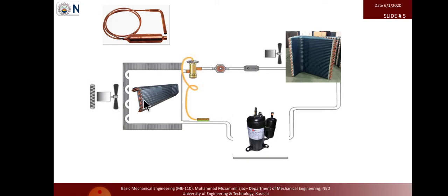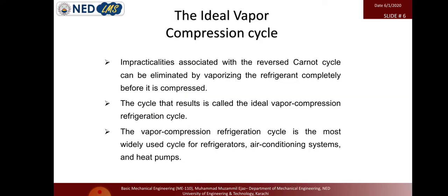It evaporates at 12 or 13 degrees. When the room temperature air passes over here, it contacts the refrigerant with room temperature like 25, 26, 27. So the liquid refrigerant gets boiled or evaporates, and that evaporated refrigerant again goes back into the compressor. This is how the cycle goes on.